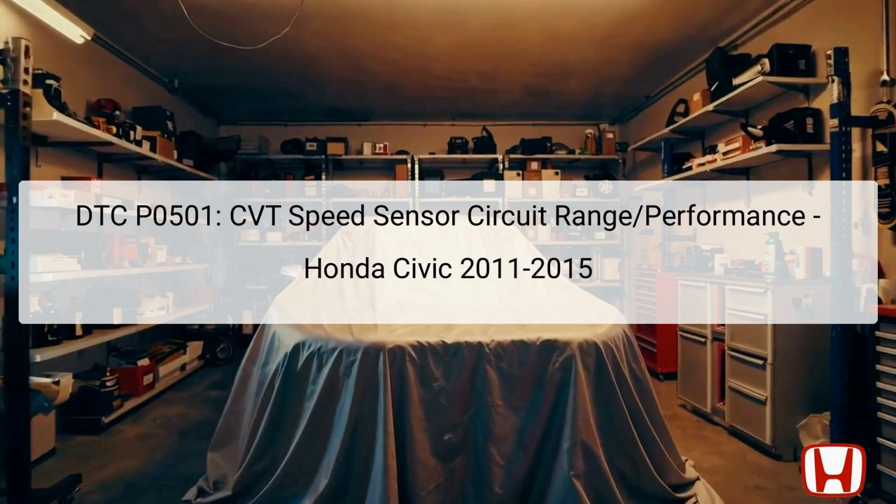The CVT speed sensor is a crucial component that measures the speed of the transmission input shaft. It sends this data to the Powertrain Control Module, PCM, which uses the information to optimize engine performance and ensure smooth driving. The code is triggered by electrical circuit problems rather than any mechanical issues within the transmission system. Therefore, diagnosing and resolving this code requires a thorough examination of the electrical connections and the sensor's functionality.